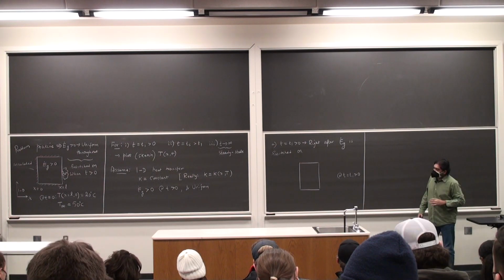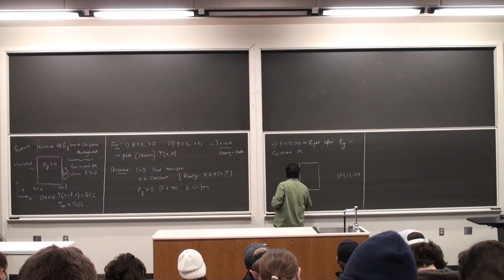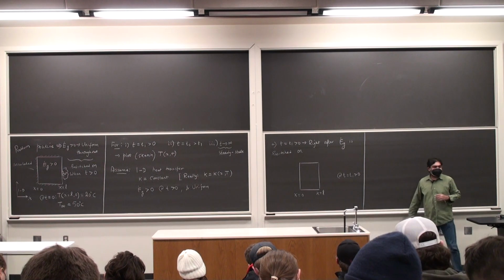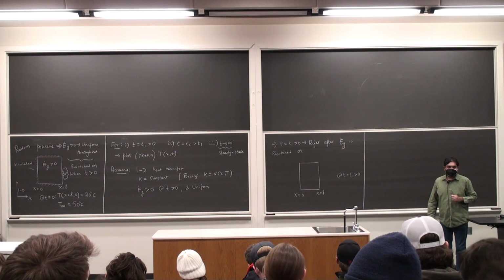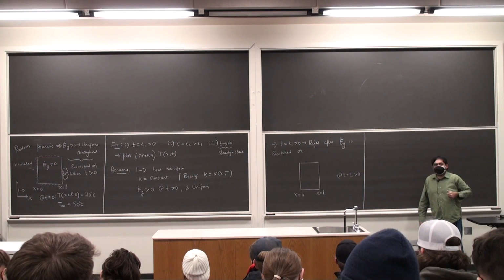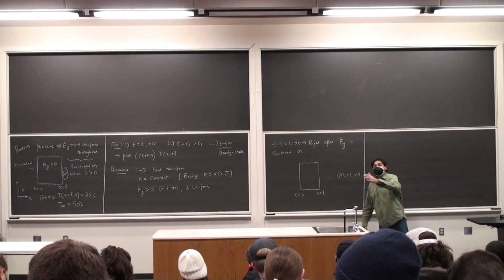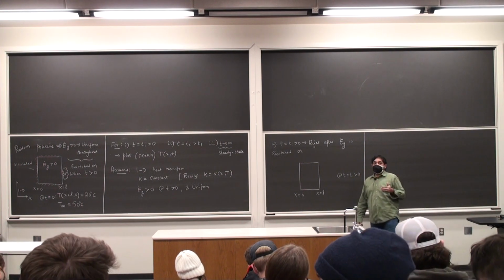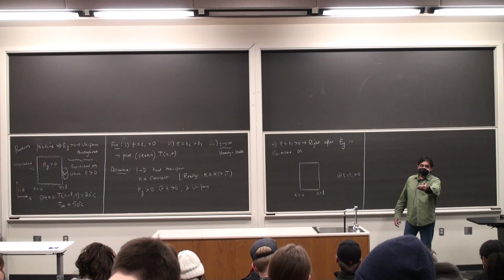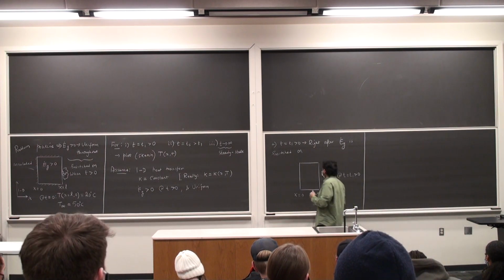And you're going to tell me at the location x is equal to 0, what should be the slope? Should be 0, right? Because the side is always insulated. So no matter what I do, at whatever time I'm looking at, either is it at steady state or at the beginning of the problem, the left side of the wall will always see a 0 slope for the temperature gradient. Okay? So the slope is 0.